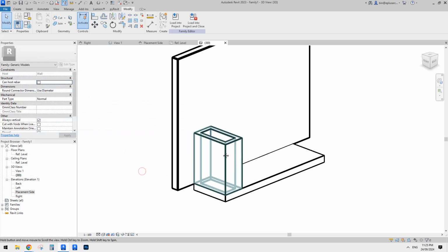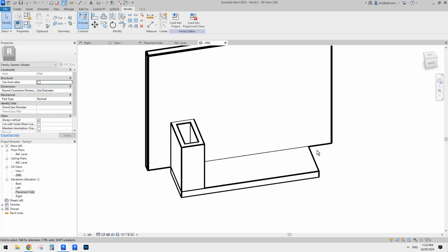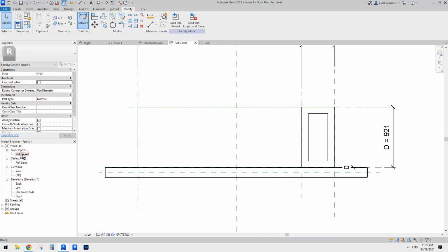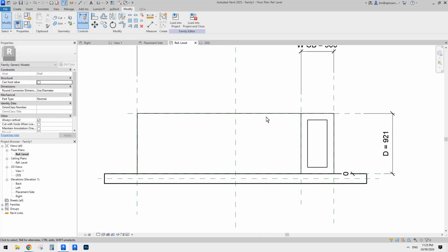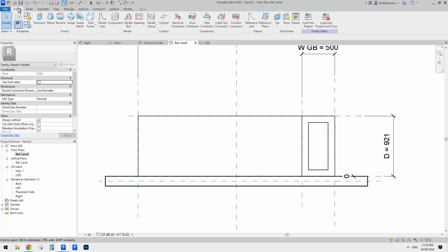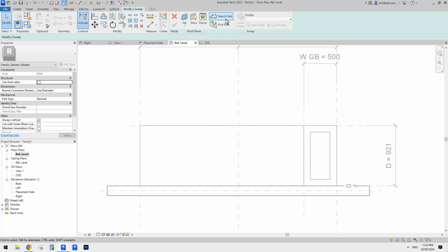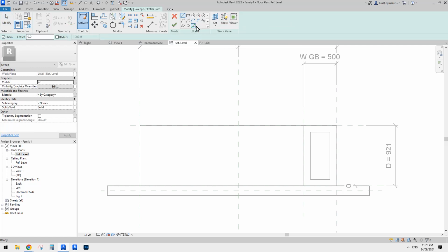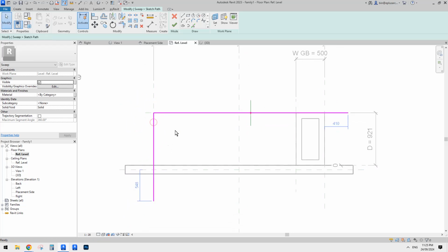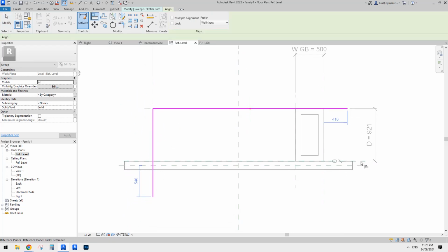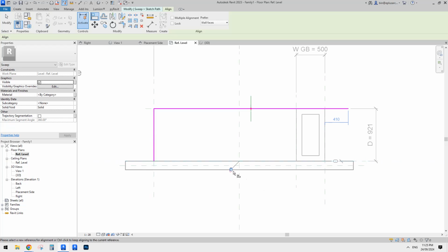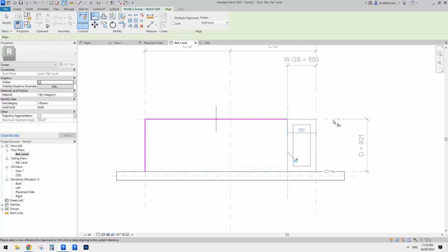Okay, so now we have this, and then we need some railing, right? It's also quite simple. So let's do a top rail first. For the top rail, I'm going to just do a very simple sweep. Okay, so sweep, and the same, I'll use sketch path and pick line. Pick this reference plane, so I'll have this locked, so it will directly lock onto this reference plane, and also this one, trim TR, and then AL line, so use this and pick this endpoint, lock, and also here, and lock.